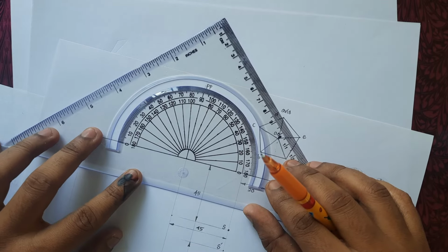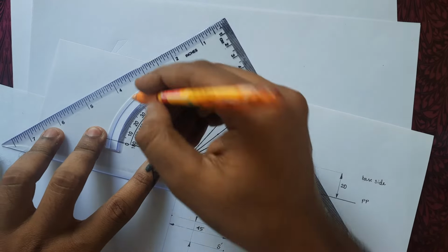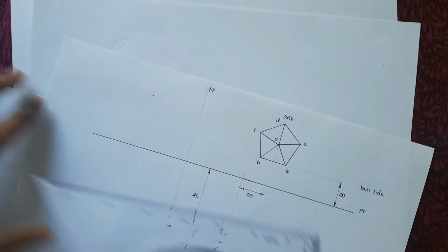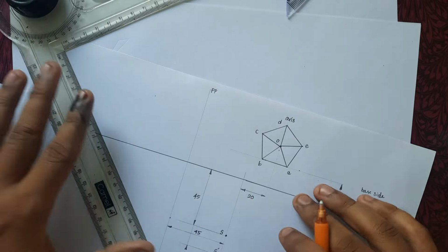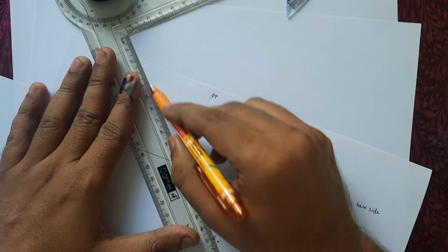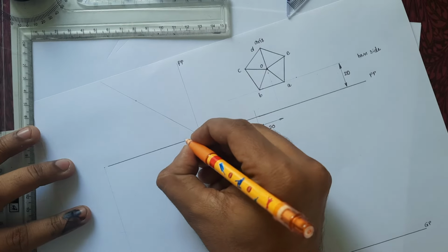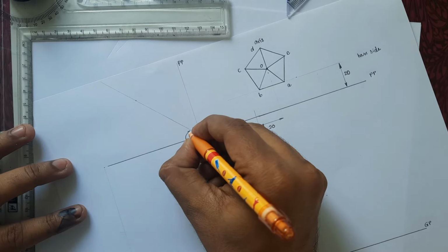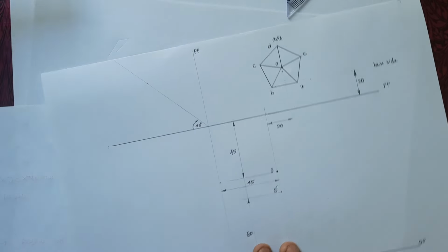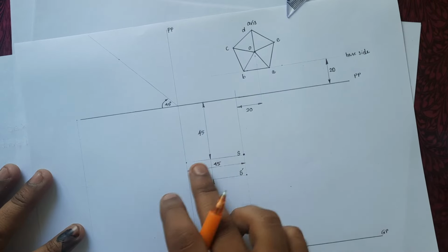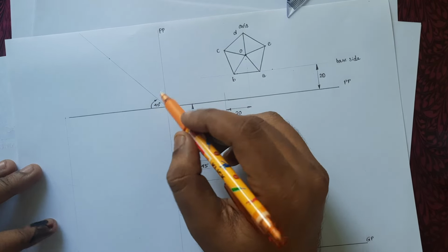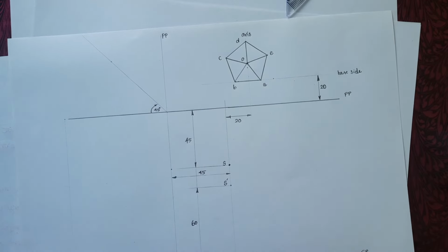Yeah. And next we need to divide the second quadrant into two, because we are going to draw the side view. For the side view, we need to divide the second quadrant into 2. So we can take 45 degree and divide the quadrant into 2. For all the problems, it is 45 degree only. The distance may vary from problem to problem, but by dividing the quadrant into 2, we always need to take 45 degree.